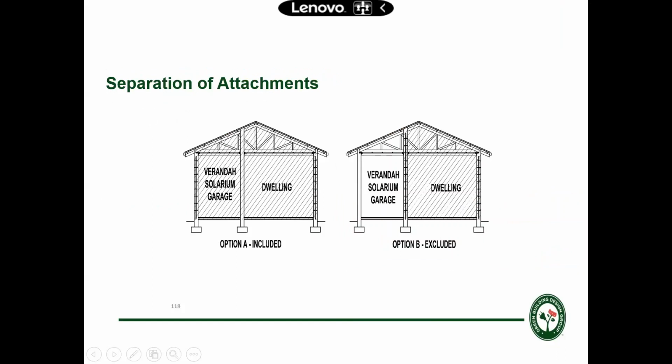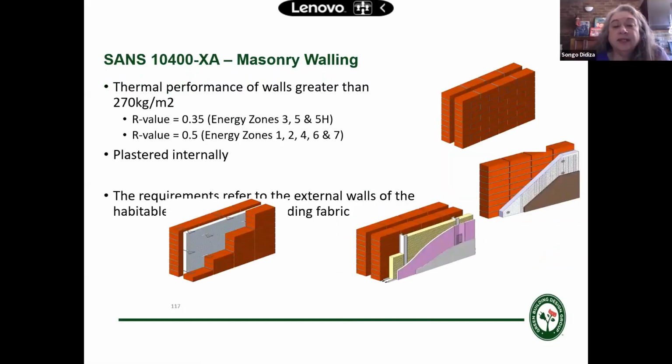So again, when I say you mustn't fill a cavity wall with anything, you obviously can fill it with insulation, because that has an insulating property and it's got an R value. So it's got a thermal resistance. It prevents the ingress of heat or the outgress of heat.